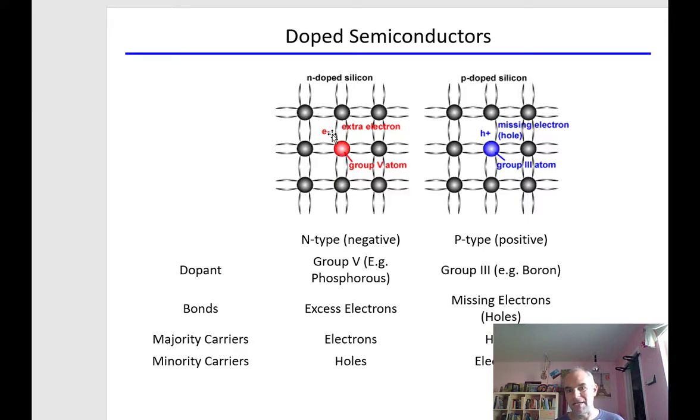So naturally, the electron that's on this side wants to go to the hole on that side, and vice versa. And I guess you can think of when the electron moves, the hole does as well. And so then you get this region that's called a diffusion region in between the two materials, somewhere in here, where you have electrons kind of invading into this side and holes invading into that side.